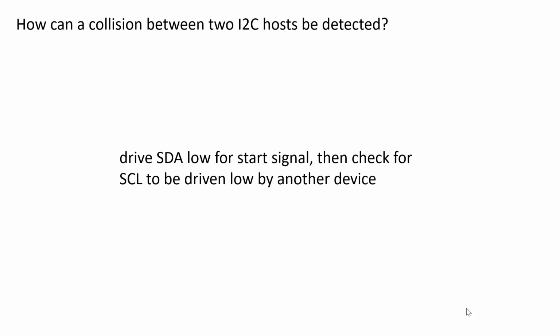Like if everyone's doing this, would that work? I mean, you drive SDA low, you wait for someone else to drive SCL low. I guess it would work as long as they don't wait exactly the same amount of time, because then they would be perfectly synchronized.